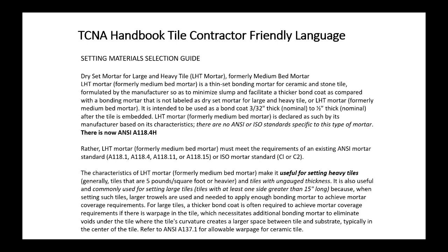Where large tiles are used, this comes in handy when you've got warpage in tile. The larger the tile, in the case of plank as an example, almost all of that's always in the middle, in the center of the tile, and can be quite a bit off the ground, off the floor for that matter. And without having good bedding of material, it's going to sound hollow, you have potential for breaking and so on. So where we really want to have a good bedding of material to make sure that we get good coverage, these large and heavy tile mortars are excellent.